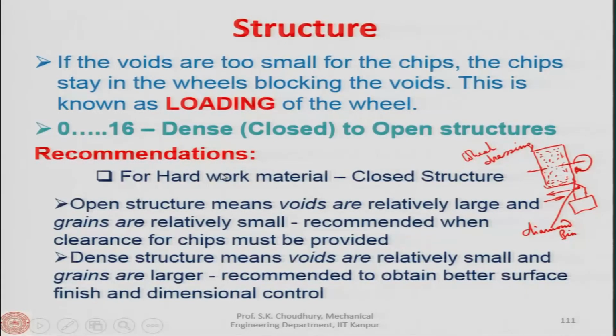Now, the recommendation is that for hard work material we should select the closed structure, with grades like 0, 1, 2, 3, 4, 5. Open structure means voids are relatively large and grains are relatively small, recommended when clearance for chips must be provided.